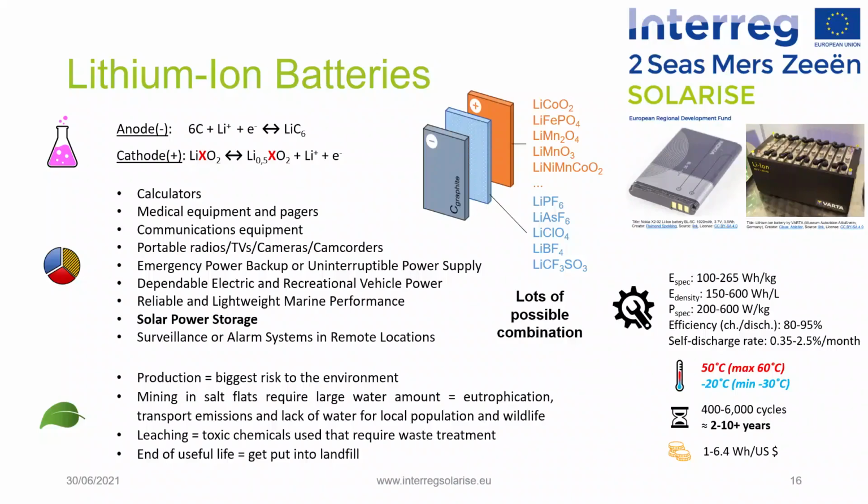These non-aqueous electrolytes typically use anion salts as listed here in light blue. Depending on material choices, the voltage, energy density, lifespan, and safety of a lithium-ion battery can change dramatically. The current effort has explored the use of new architecture using nanotechnology to improve performance. Areas of interest include nanoscale electrode materials and alternative electrode structures.